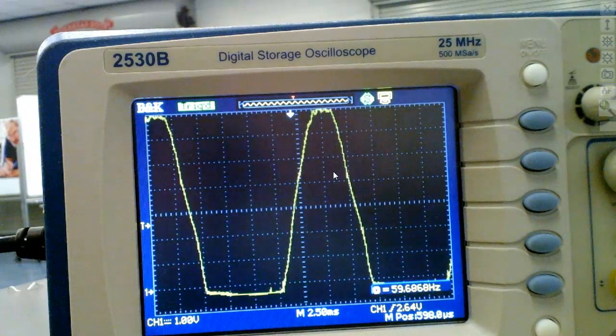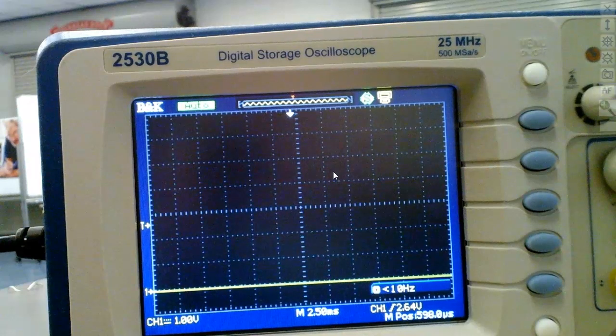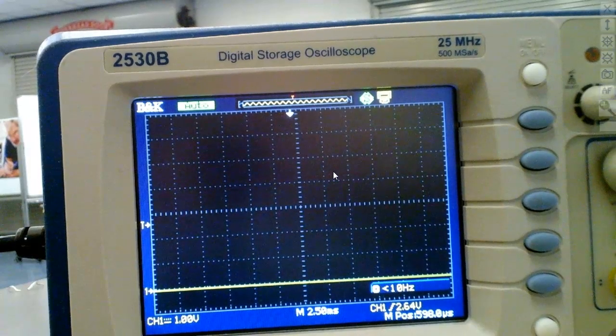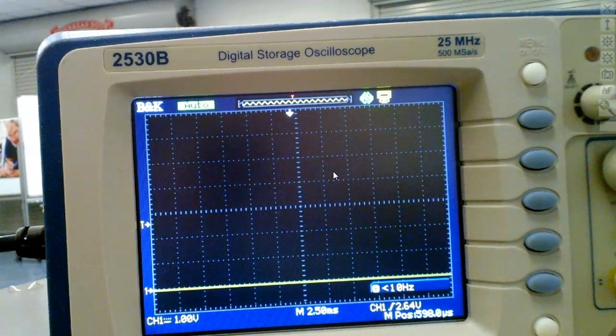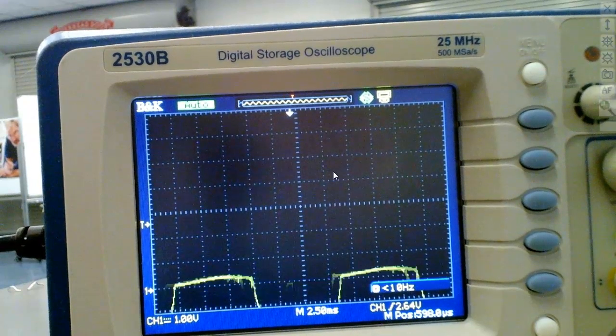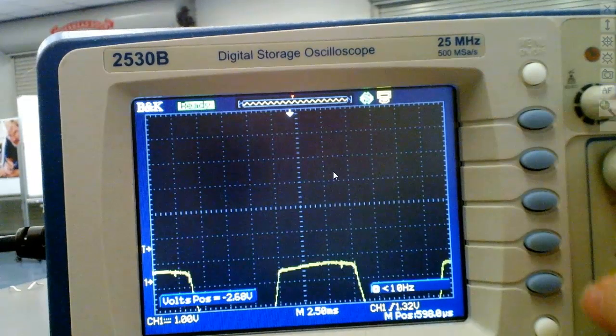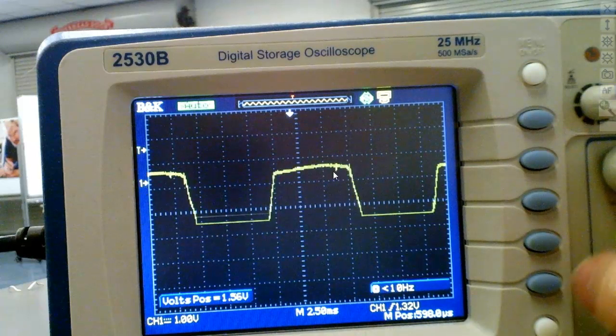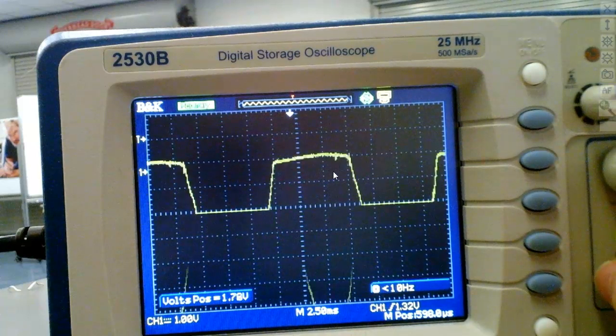And of course, all I need to do to change the polarity of the waveform is just reverse the diode. Now, normally you wouldn't do this on an active circuit, but we only got 7 volts there, right? So now all of a sudden, when I hook this back up, now we have negative.